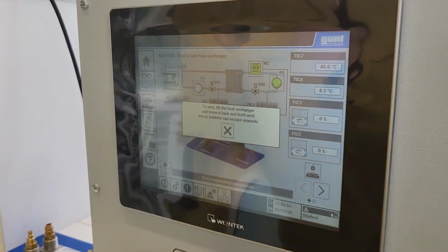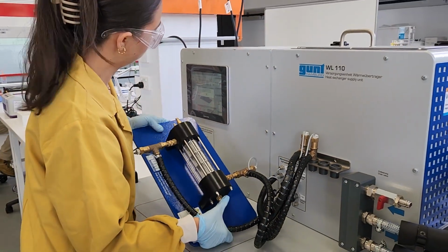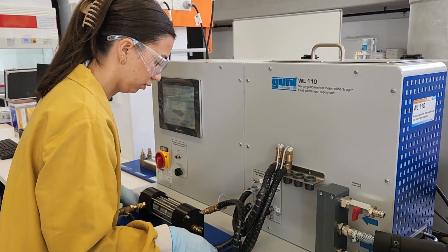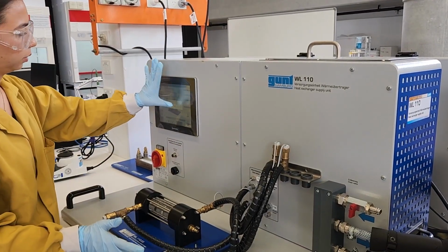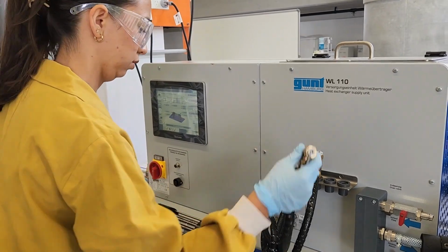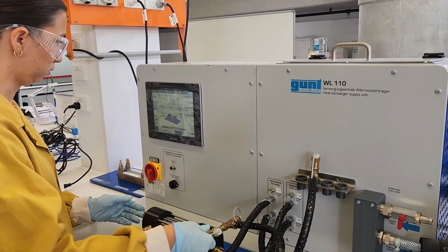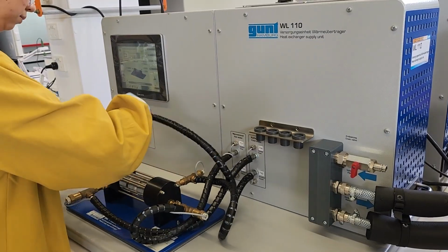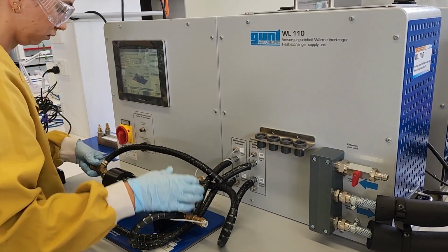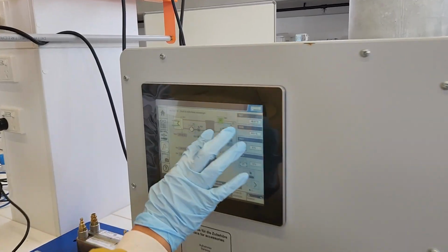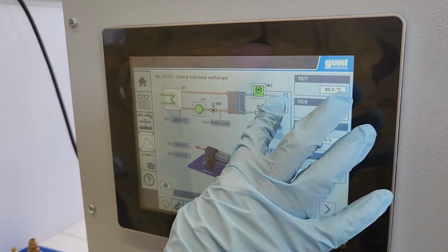And now you can lift the heat exchanger without the system changing anything, so that you can move it back and forth to remove those bubbles. Once you've removed hopefully most of the bubbles, you can go back and just set up your hot water. And just turn on your pumps again for the hot water and for the cold water.